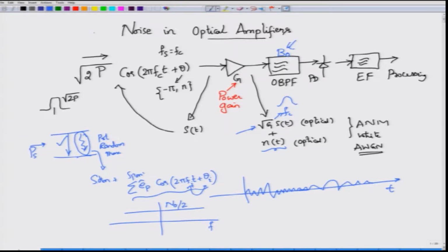So, that is why we model this as an ideal band pass filter. After filtering, the noise would not be just n of t, it would be a different version, while the signal is more or less unaffected, because the signal, as we have said, is within the bandwidth, therefore it passes through the band pass filter with very little distortion. We will assume no distortion here, but the noise gets filtered. Let us call that filtered noise Nf of t.